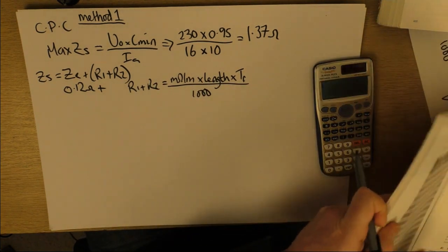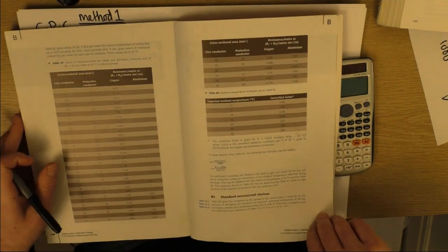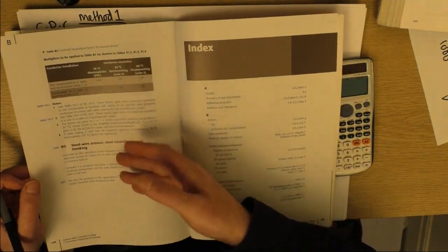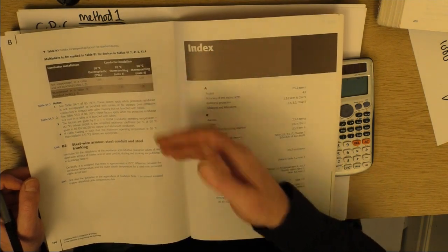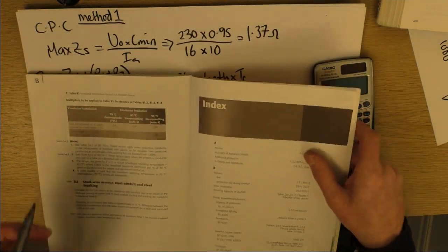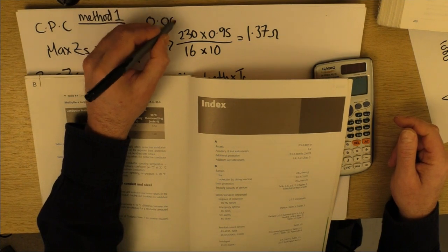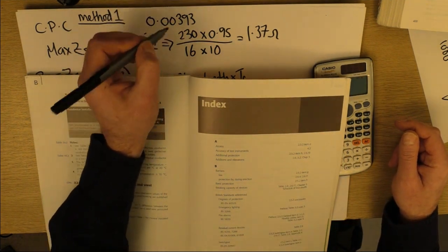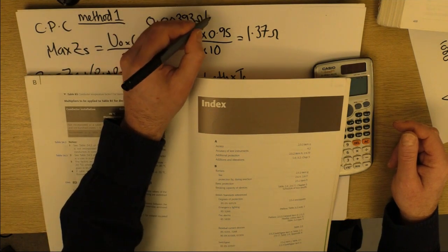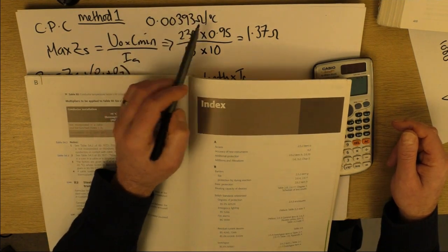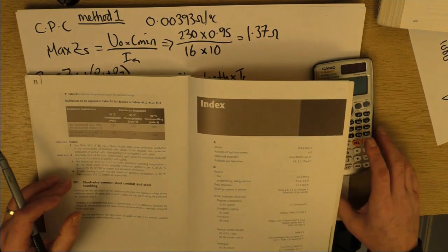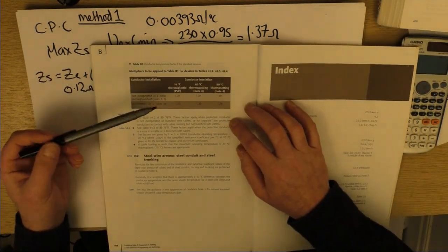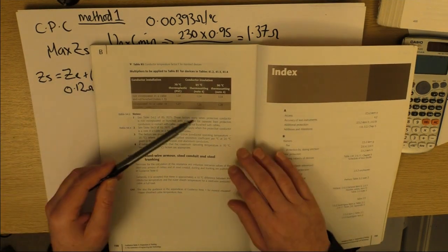Temperature factor, and that's been done for us, but just know that these correction factors have been done for us. It's just down to the fact that copper increases its resistance by 0.00393 ohms per degree C. I've done a video about all this, so check it out if you're interested. But for what we're doing, we need to use this factor.